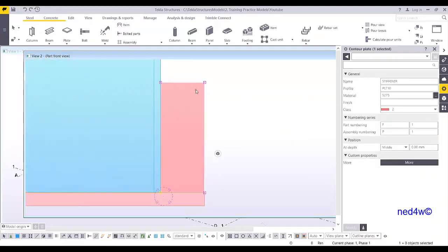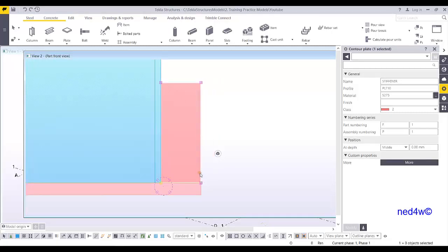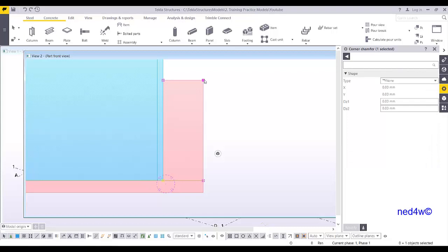Since I have a 25 cut here and a 25 cut at the top and bottom, all I have to do is to change this chamfer. For the chamfer, I can use the line, and then the distance, let's say distance x, if that one is 10 and I have 25 remaining, so 75, and then this one is 225. Let's see if that one is correct, x and y. Oh, it's the other way around, so just 225, and then this one is 25. Sorry, 75.